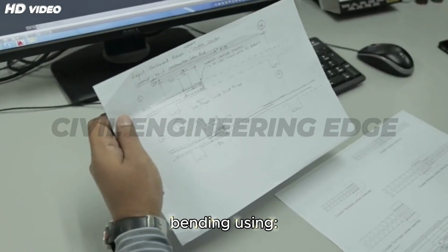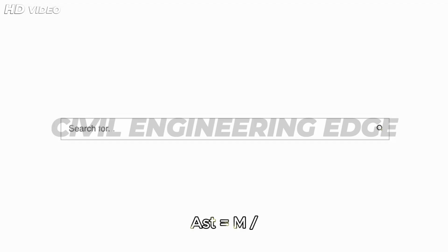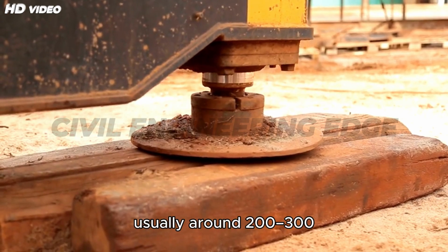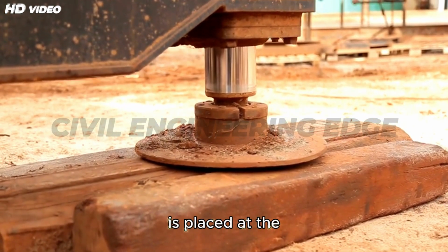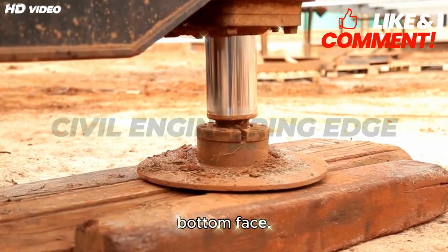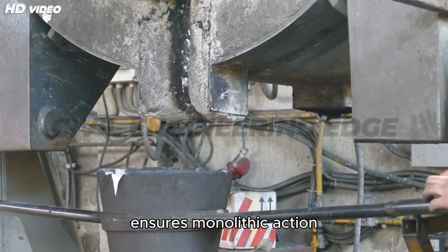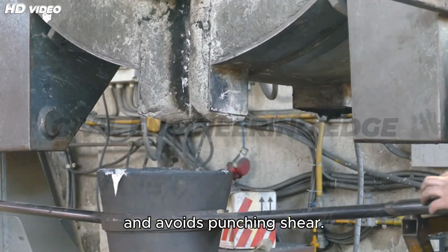Design the slab for bending using Ast equals M divided by 0.87 times fy times d. Minimum reinforcement must be ensured as per the code. The slab thickness is usually around 200 to 300 millimeters, and tension steel is placed at the bottom face. Proper anchorage at the junction with the stem ensures monolithic action and avoids punching shear.